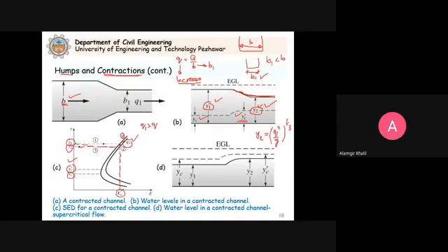And if we have a supercritical flow, in this case D, we see a supercritical flow. Why supercritical? Because Y1 is less than YC. There is a slight increase in the water surface from Y1 to Y2 here, but the flow remains supercritical because it is still less than YC dash. So this is how these specific energy concepts help us to analyze flow problems.